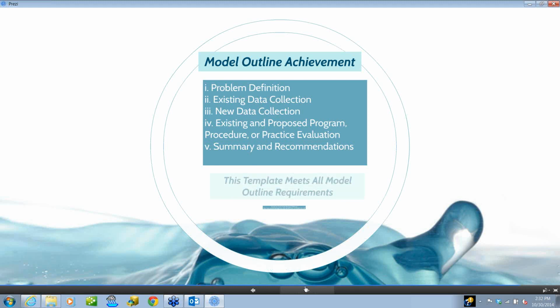And then looking at and making some conclusions about how the existing stormwater management regulations in the town would be applicable, would be useful for managing existing but then also future flows, and potentially what some improvements could be to the existing regulations in order to better manage these higher flows, specifically which were determined to be in kind of a core area of the town. It was determined that there was a focus area of the town which, based on the zoning and the effective impervious cover, based on the modeling work that was done, was really going to be subject to much higher flows in the future. And so how could regulations mitigate those higher flows if development will continue?